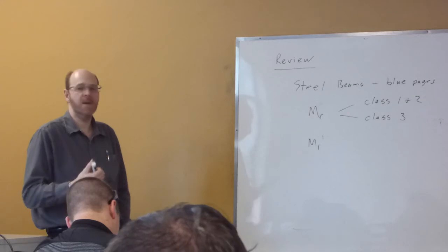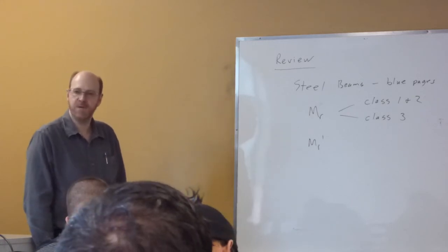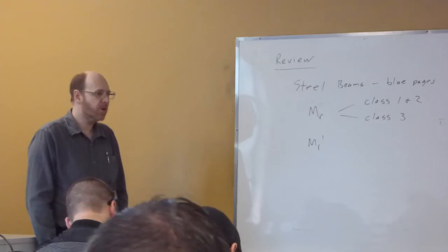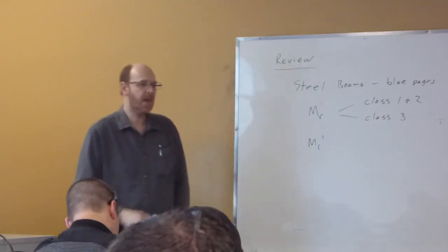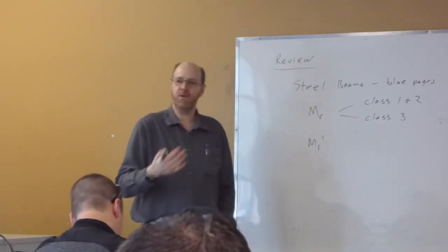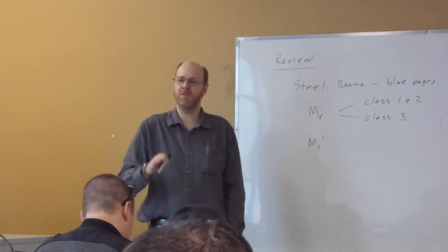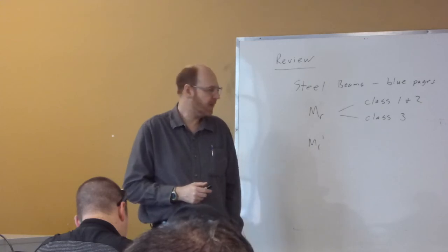And then the last stage is when the concrete is set up sufficiently and we have full composite action. And here for our full composite action, now we're looking at the full design load case that we're considering. So all the dead load and all the live load for our service condition and that 3 case.